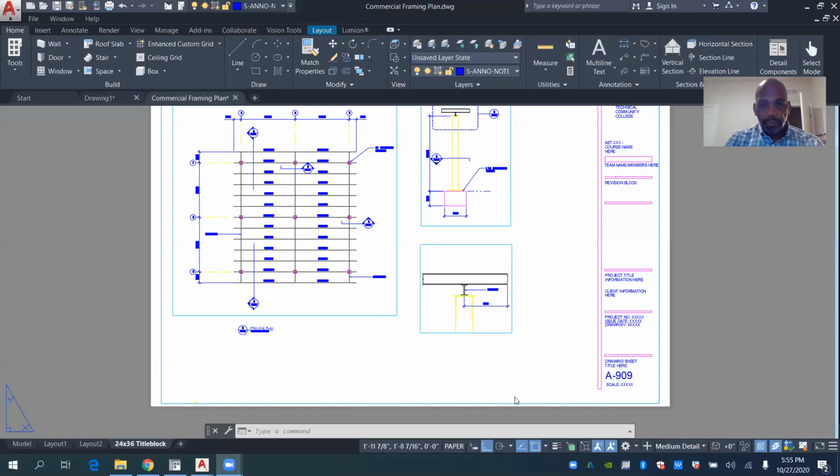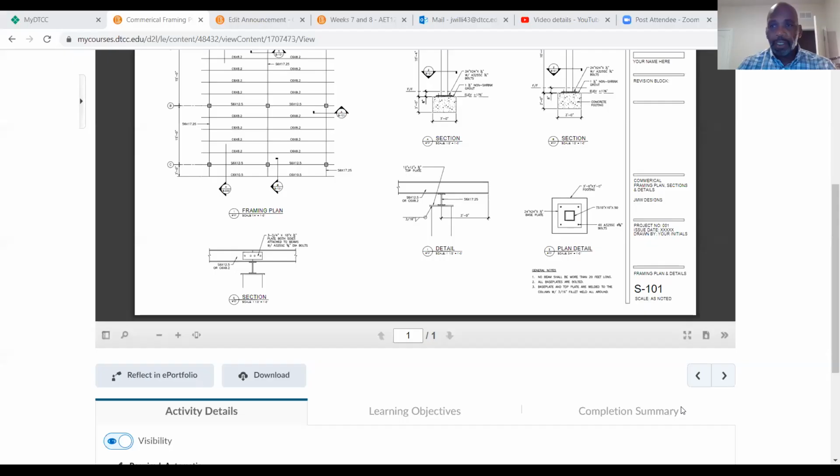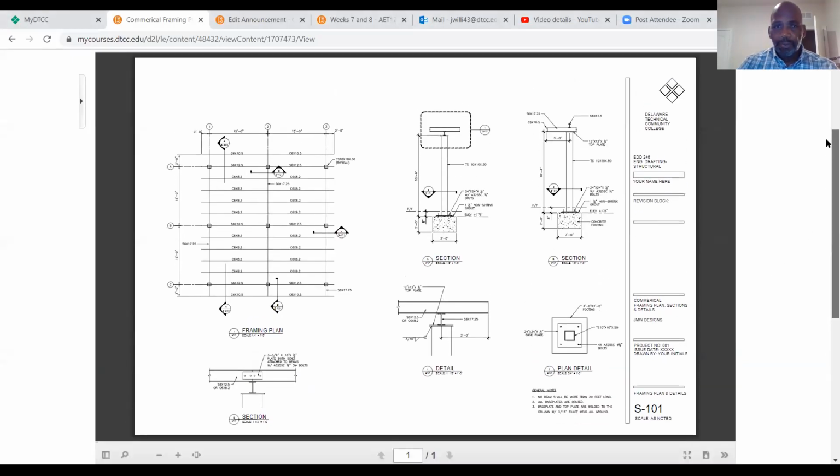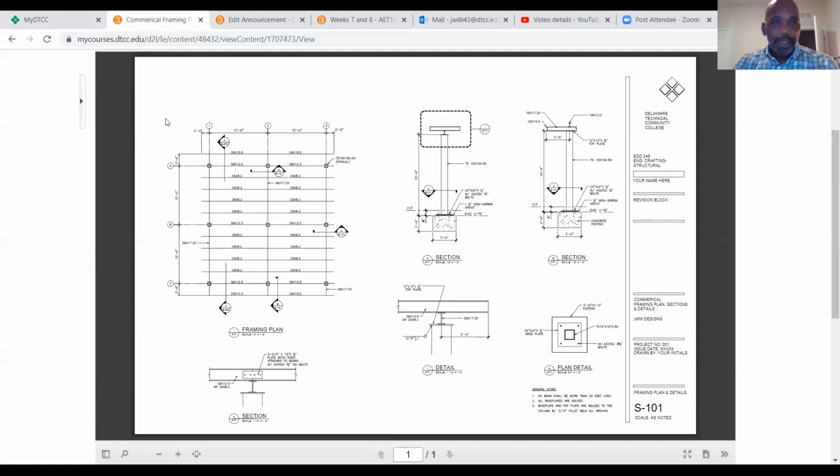All righty. Let me pause for 1 second here. Okay, I paused to take a second look at the sample drawing. Okay, good. So now in paper space, just to reiterate, we have the framing plan, having a viewport scale of 1/4 of an inch. Okay, annotation scale in paper space also being 1/4.